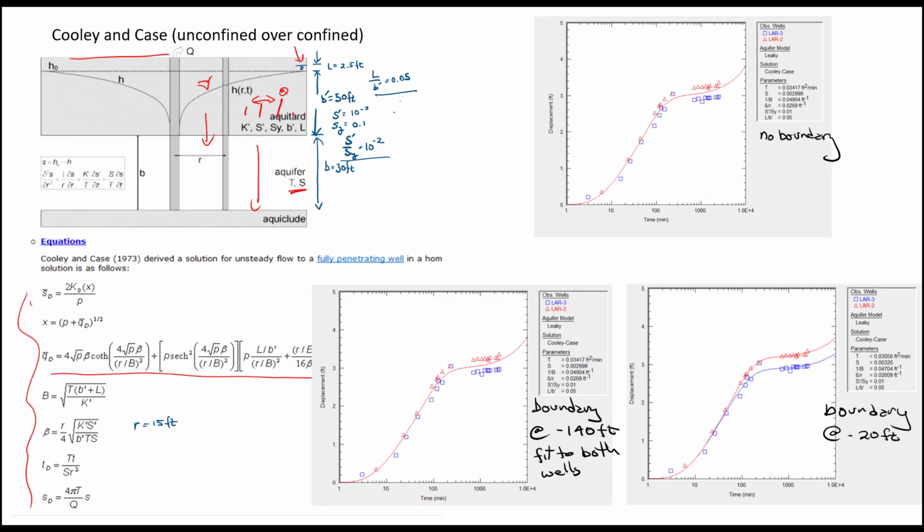So I went through the conceptual model and came up with some of these dimensions, for example, the thickness here. And hold on just a minute, I gotta turn on this pen. For the thickness, there's the capillary fringe, and I need to have an estimate for the storativity of the confining unit of the saprolite and the specific yield, and I need to have their ratio.